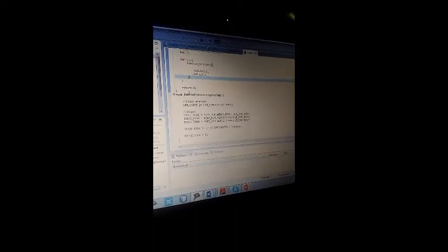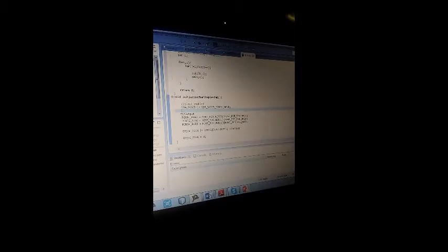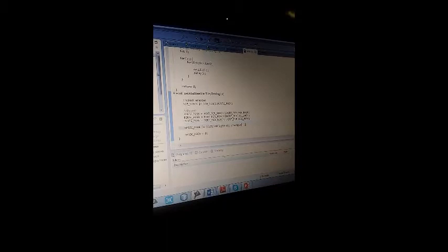So in our main function, first we initialize the Charlieplexing. It will be the same as the initialization back in Lab 4 Part 1, but some small changes have been made. In this case, it's the same thing that we enable the clock for port C. Next, we set the outputs for PTC3, PTC4, and PTC5. The port direction PDDR has been set, while we initialize all the PDOR to be 0. In this part of the lab, we don't have an input, not like our part 1.